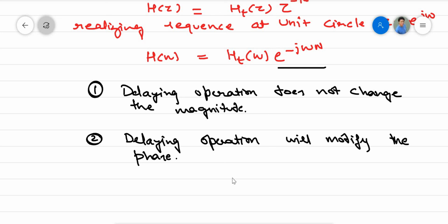Then one can say the design process for an FIR filter involves truncating the infinite length impulse response h_d[n] of the ideal filter and then shifting such response to make the filter causal. Now one may ask why we want to make an FIR filter. For that we have already discussed certain points in the previous lecture and I will address those points right now also.